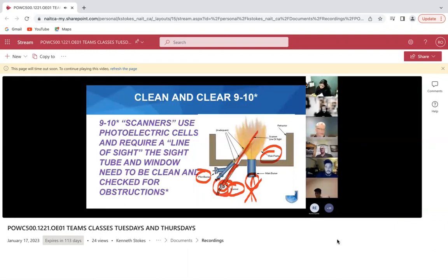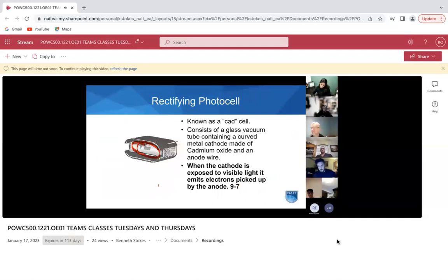If you've removed it, you're going to shut down the gas. You won't see a flame, but you should be pointed at the flame. And the devices have meters on them that allow you to adjust the angle to get the strongest position to aim them at the flame.